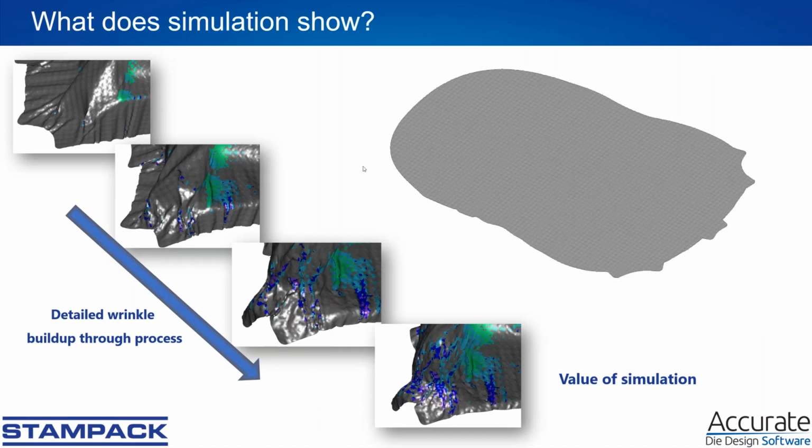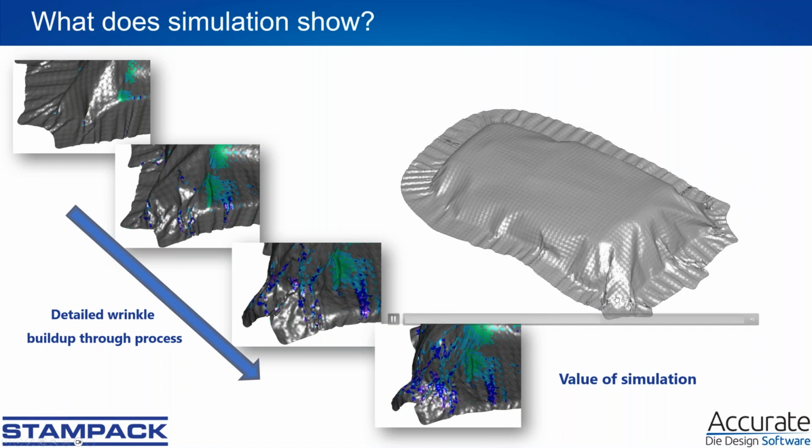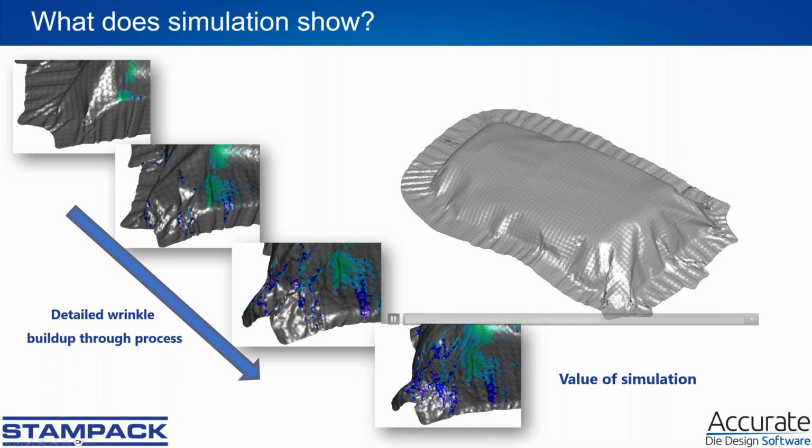What you can also see in Stampack is how the wrinkles appear during the process. So we have here an embossed sheet. That is what people use to make heat shields. And here you see that in Stampack we simulate including the embosses. And during the process you see very well how the wrinkles appear. In this kind of process, wrinkles are allowed, maybe in some other processes not, but they are predicted by simulation, and then you can judge whether you like the wrinkles or not. So in this case, it's allowed, but maybe in others not.